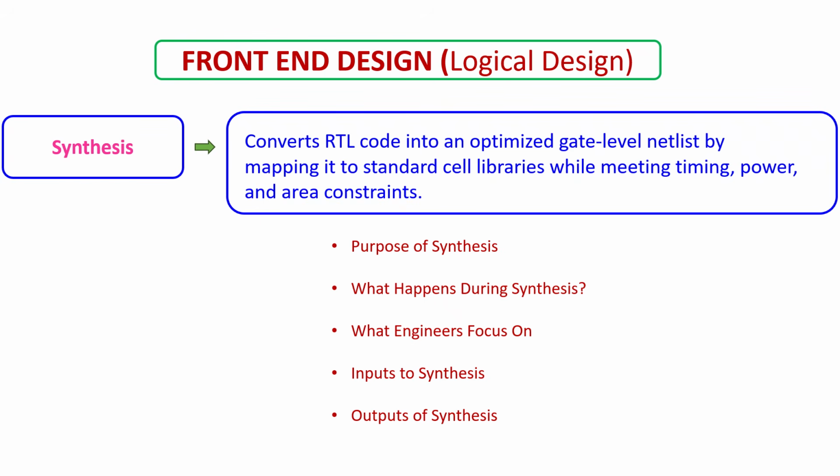What is the purpose of this synthesis? This converts the RTL into a gate level netlist. It maps logic to standard cell libraries, and it optimizes for timing, power, and area. This stage prepares the design for physical implementation.